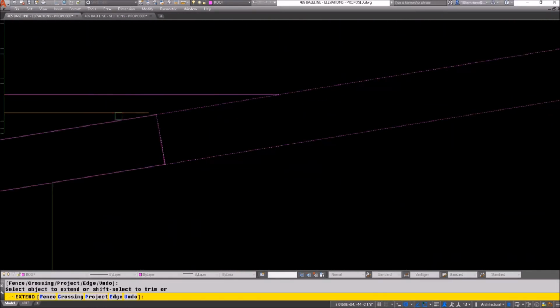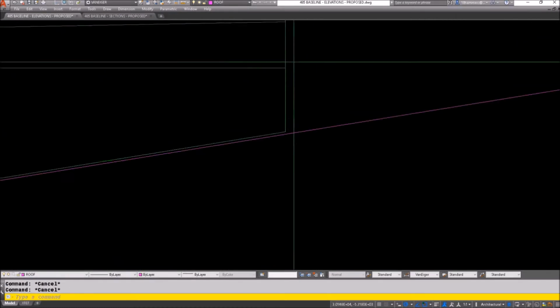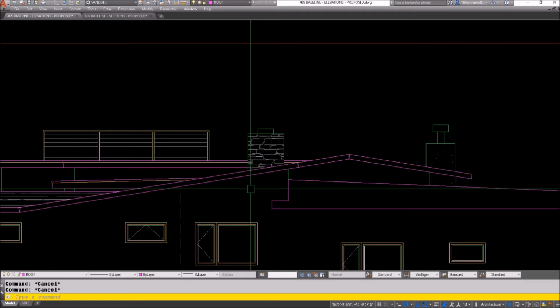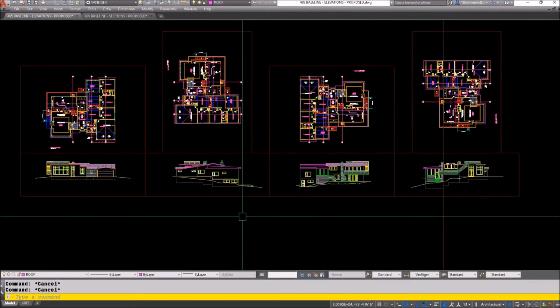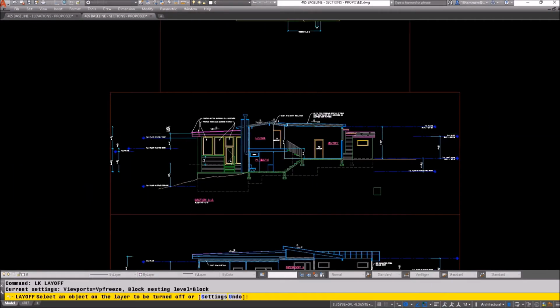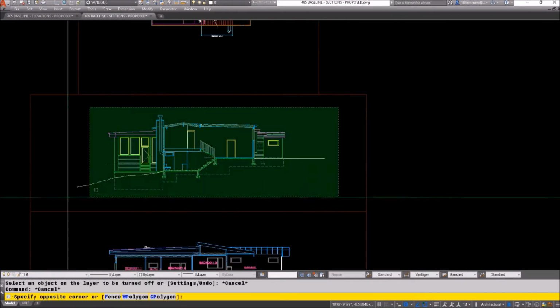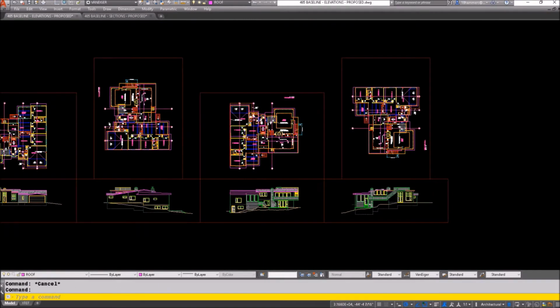What's going on here? This is more roof, catching the roof up. So it's got the right height on it, and it matches the sections. Sometimes I'll draw the section first, and then I'll come back and do the elevations. So you can see all 4 elevations with the XREFs above them. That's how I project down with the construction line. And I have my construction line programmed to my right click.